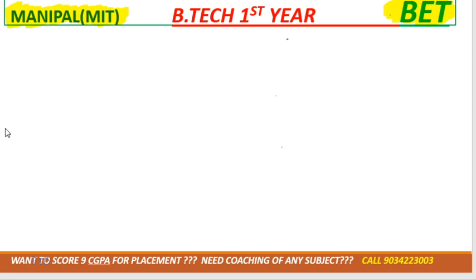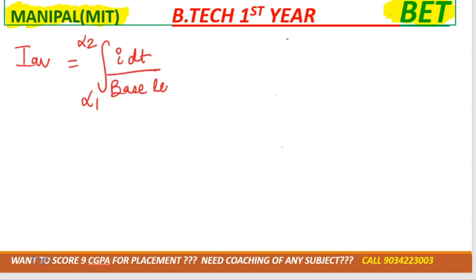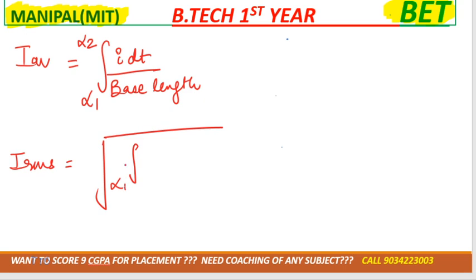Now after that, in this they'll ask you to calculate I average. So write down the formula for that. I average formula is integral from alpha 1 to alpha 2 of I dt over base length. I'll tell you what is base length and everything. We'll have IRMS. IRMS का formula is root of integral from alpha 1 to alpha 2 of I square dt over base length. This is the standard formula.